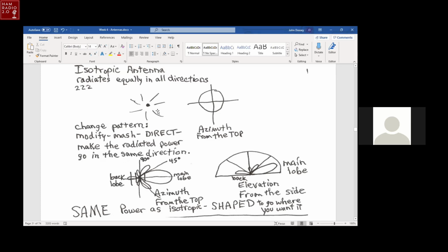A dipole has a pattern broadside to it. Those quarter wave verticals we were looking at, you can make it go linearly off the axis of the two quarter wave verticals. You make it go broadside, depending on how you phase the feed to it. You can make it go cardioid, where there's a null in one direction and it's nearly omnidirectional all the rest of the way around it, just by the spacing and how you feed those.